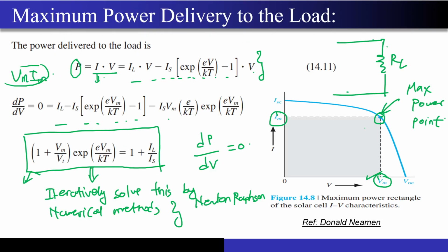So if you just go into this curve, right? Now if I go to the right and if I operate at the maximum voltage that I can get, that is the open circuit voltage, right? Then I don't have any current with me over here because the current will be zero. Now similarly from this particular Im, if I go up, I will get an ISC and I don't have any voltage over here, right?